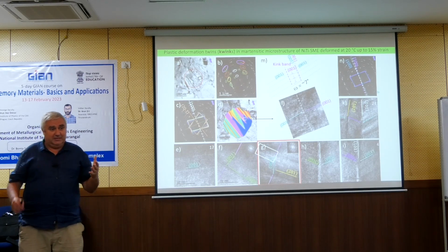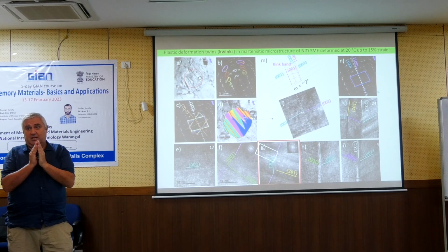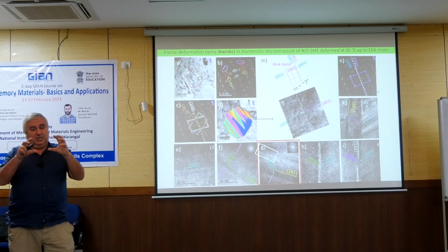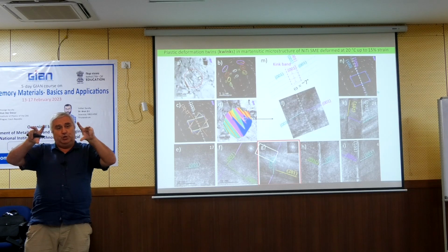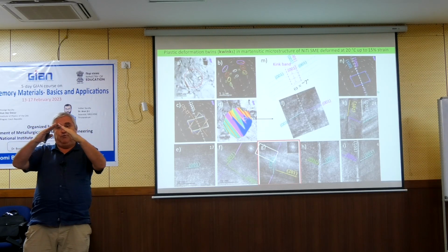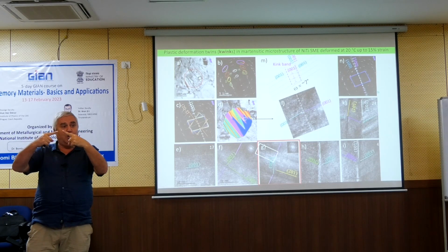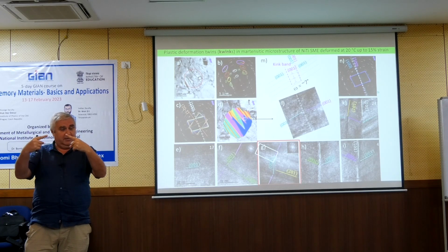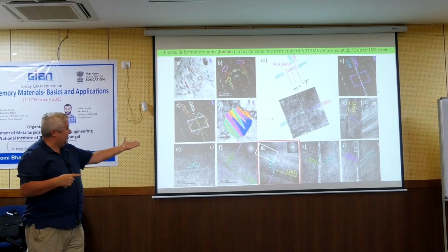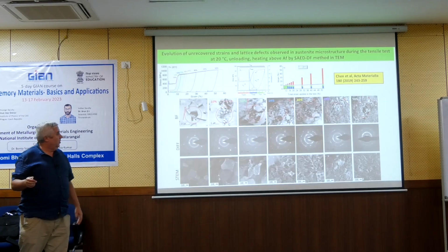It is still the same. The material can only create an interface which is strain compatible. And of course, if you have the shape strain, some kind of shear, and you imagine two sheared microstructures which should form a compatible interface, it has to be a mirror plane. And because this shear is always a shear on the 001 plane, you can use the traces of the 001 plane as evidence, and you will get such a pattern. Yeah. So I will talk about that more later.